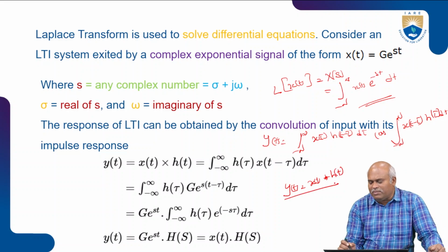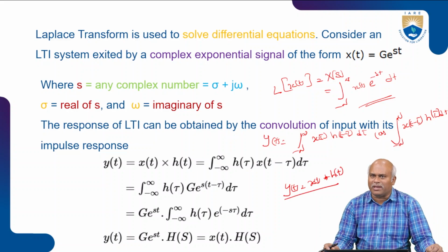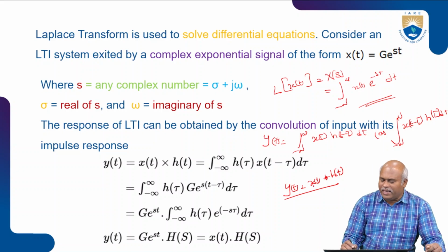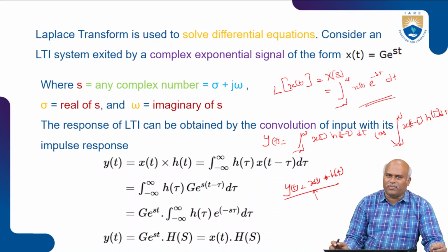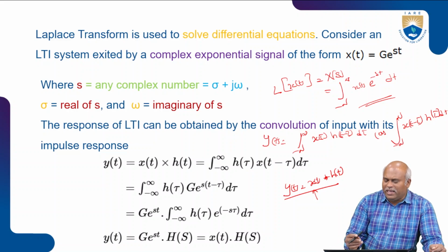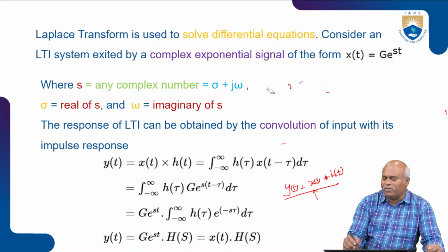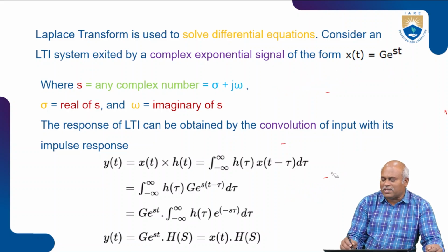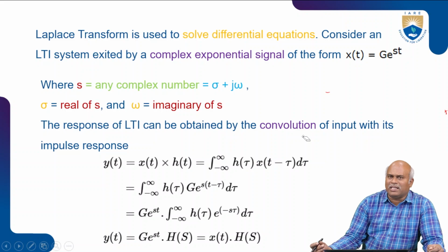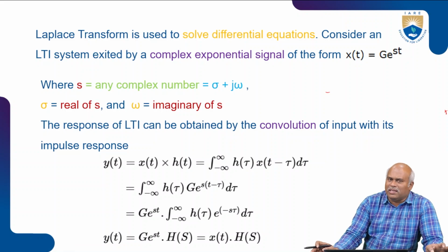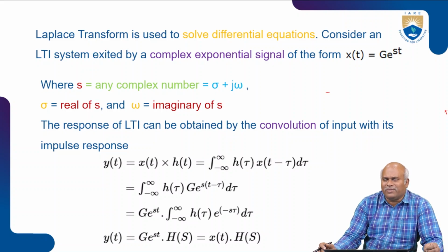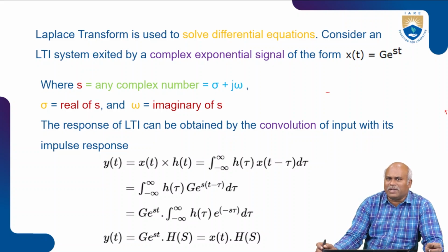We called this term convolution when we studied signals, and we derived the convolution equation also. Here I take the LTI system, meaning linear time invariant system. It satisfies the superposition and homogeneity conditions. If both are satisfied, then the system is called a linear system. The linear system produces an output represented as the convolution of the input with the impulse function.